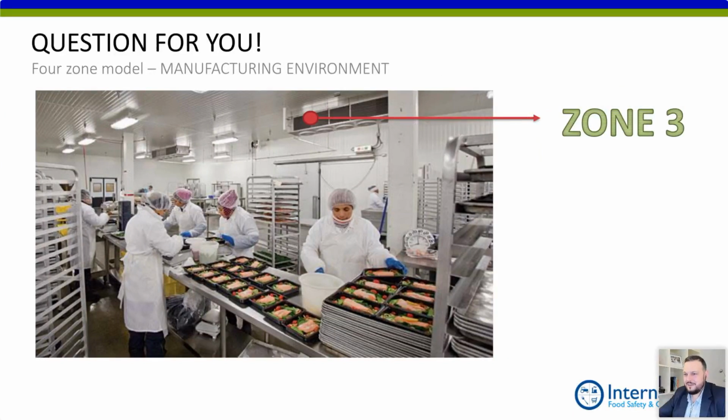Yes, it's not in direct contact with product. It is not going out, but it is taking air from the outside, or from some outside system, that goes inside. So probably we will take some sampling of the air, and we can call this zone 3 then, because this is the air conditioning or the ventilation system. It is not going outside, but it is taking something from the outside and entering inside, an air handling unit.